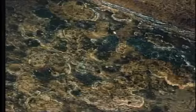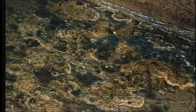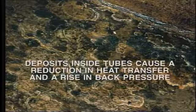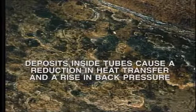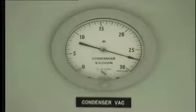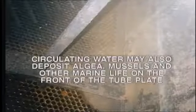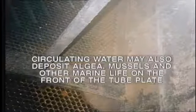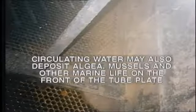Over a period of time, the circulating water may leave some deposits inside the tubes. The consequence of this is a reduction in heat transfer and a rise in the back pressure inside the condenser. This results in a loss of efficiency and lower output from the turbine. The circulating water may also deposit algae, mussels, and other marine life on the front of the tube plate, reducing the flow of water through the tubes.